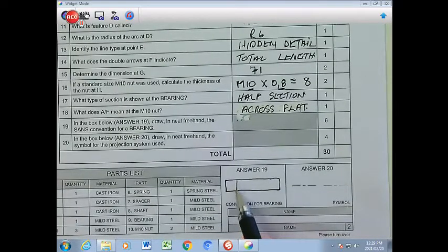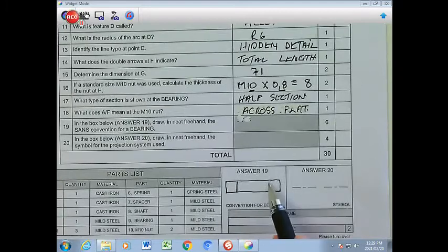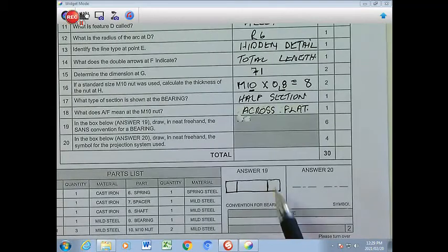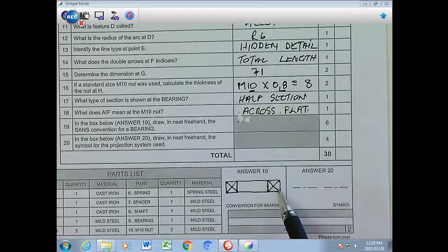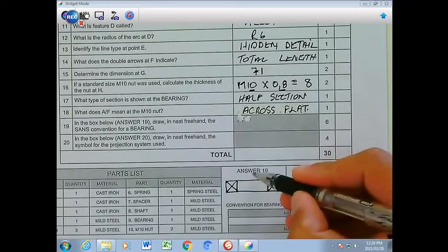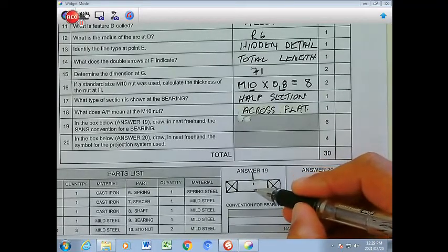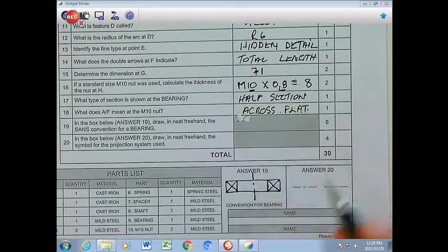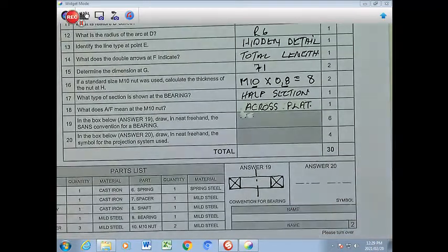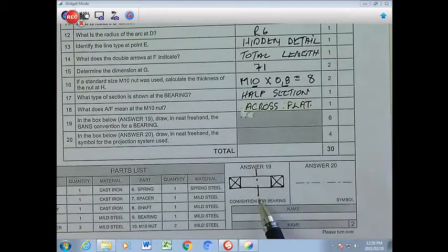And then one side will be the one part of the bearing and the other side will be the other part of the bearing, and this will be an actual hole here, and then you will have a cross here and a cross or diagonal at both ends. Don't forget to put in your center line, long short there, and that basically shows you the symbol of a bearing, right? Don't forget the center line, as I've mentioned, very important.